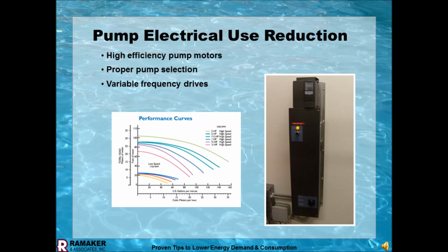And the reason is that water slide has to have a certain flow into it. And I'm not going to have too little water out there, because if it needs 800 gallons per minute, that's what you better be putting, not 600 down it. And therefore, you do the calculations. You're saying, I'm sure this is right, but I'm going to be a little bit conservative. And guess what? We have a throttling valve, a butterfly valve on it, deadheaded, just wasting energy out there.